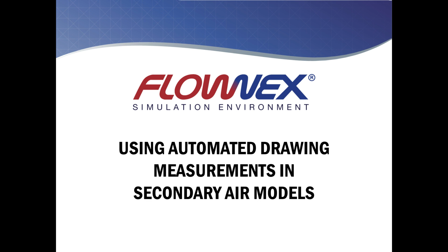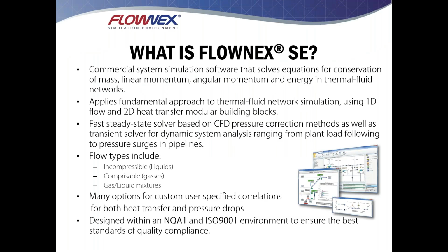Just before we get into the contents of the webinar, I'd like to explain what the software is and where it fits into the simulation world, just in case anybody hasn't heard of it. Flownex itself is a commercial simulation software. It's essentially a 1D CFD code of sorts. We use conservation of mass, momentum, and energy, and build a network out of one-dimensional flow and two-dimensional heat transfer components, and then solve that network using a pressure correction method, very similar to how a CFD solver would work. Due to the nature of the solver, the networks can be very generic. There's no limitation in how the components have to be connected, and it gives you very fast solutions.